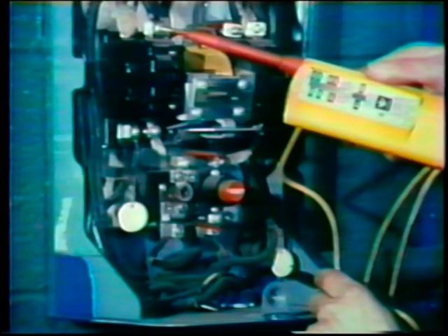But before examining the maintaining contact, the controller is de-energized by opening the power supply breaker, and the breaker is tagged in the off position according to plant procedures. Then the electrician uses a voltage tester to test the controller to make sure that it is completely de-energized. He uses the same procedures to do this as he did in the previous segment. He is now sure that the controller is de-energized and safe to work on.